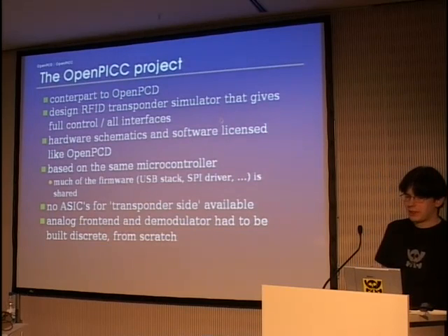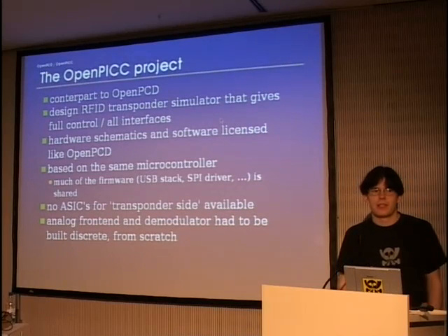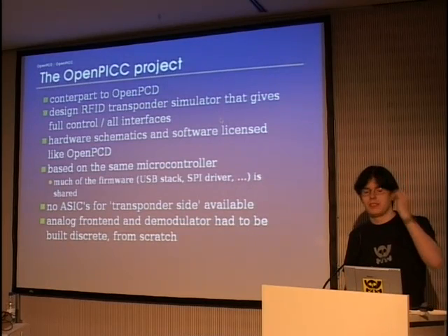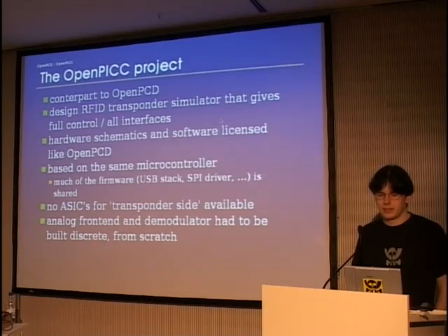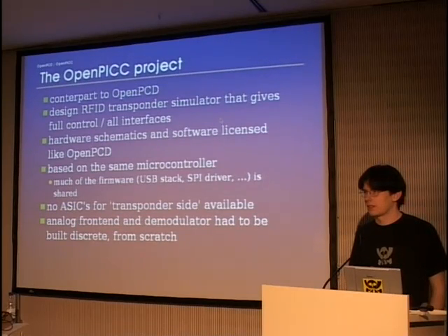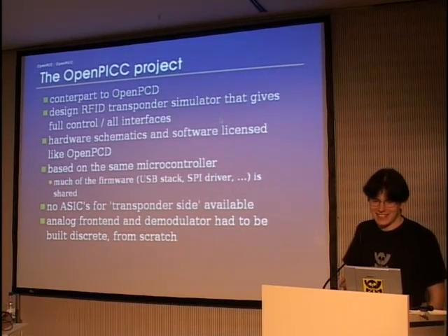So OpenPICC is basically the counterpart of OpenPCD, and the terminology, for those who are not that familiar with the ISO standards, is actually taken from ISO 14443, because PCD is the proximity coupling device, which is the reader, and PICC is the proximity integrated circuit card.